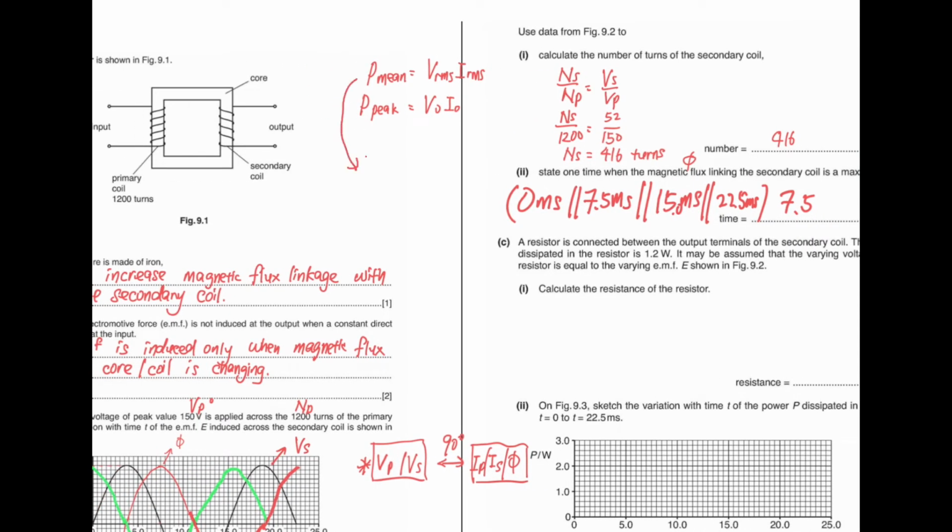So we have mean power equal to I squared R or V squared over R. So if it involves power loss or power dissipated, using these two will be better than this one. You must involve the resistance that causes the power loss.